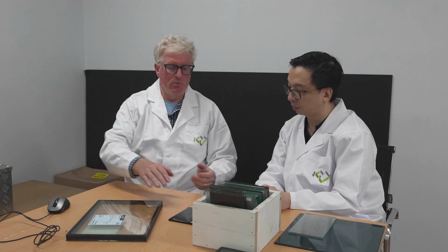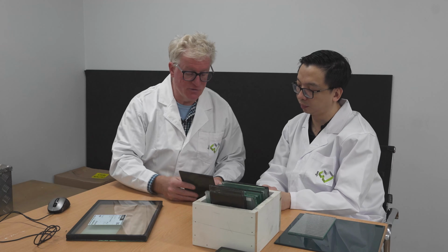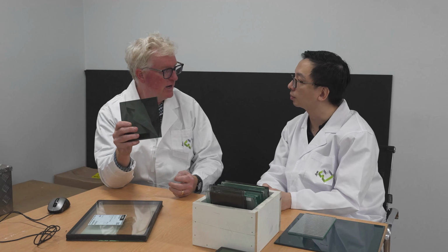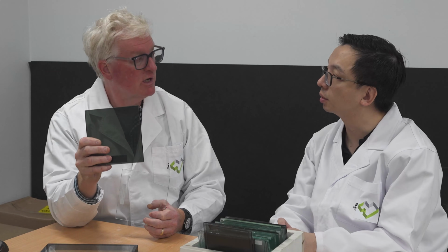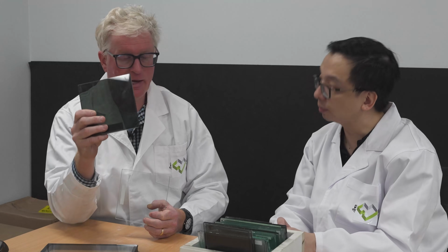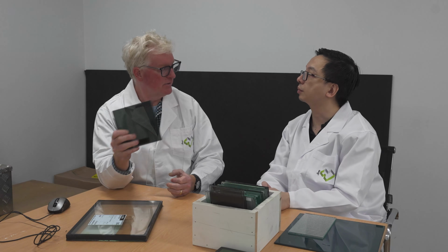Yep. And that's why we talk about designing a glazing system. We want, for instance, in a warm climate like Australia, we want to filter out the right sunlight. Yep. We want to let the visible spectrum enter through the tinted glass, but we want to reject all the other unwanted heating portions of the solar spectrum that are not related.